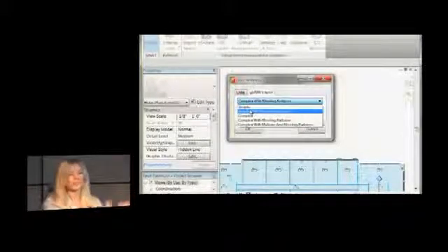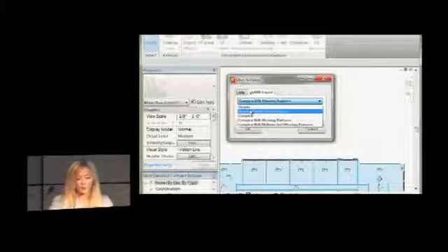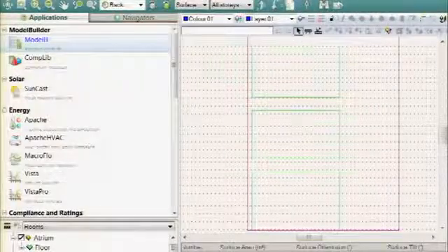make sure that they're considering the mullions. So it could be complex with shading surfaces. I think simple with shading surfaces will show the individual panes. So at least on that level, you're getting the individual windows. The error comes when they start to do a lot of overlapping of windows, like you see in this case, where the windows are not completely adjacent to each other.